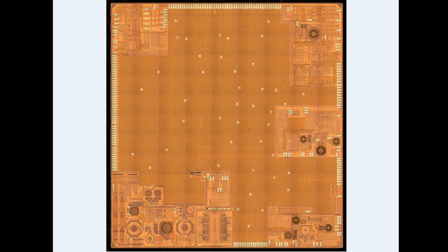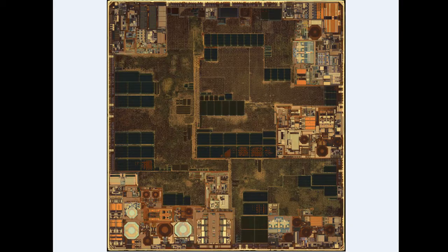The WL1283 is Texas Instruments' WiLink 7.0 device. It is one of the leading multi-band Wi-Fi chips in the market, with its major competitor being the Broadcom BCM line. As shown is the top metal layer of this WL1283 chip. Now, the chip supports the various 802.11 standards and combines Wi-Fi, GPS, FM, and what we think was the first commercial implementation of Bluetooth 3.0, all placed in a single chip.